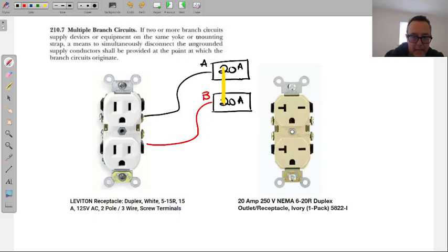It's in this section as well. But here, 125 volt rated receptacle. This is no good. You used the wrong receptacle. Inspector will look for that. In the garbage disposal dishwasher world, this receptacle has to be rated for 250 volts. Because we have 120 on A phase here and we have 120 on B phase here, meaning we have 240 at this receptacle. So this is one of the things inspectors look for.